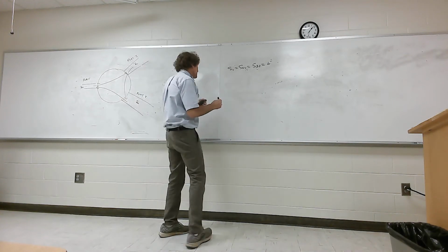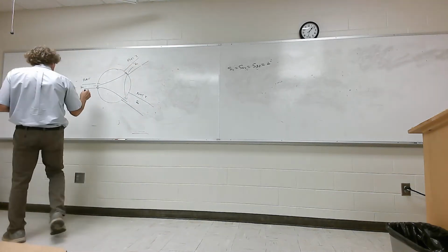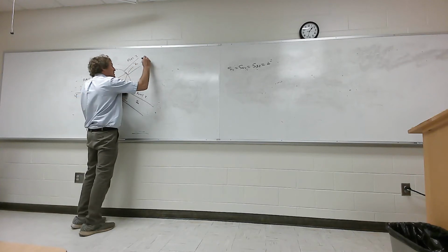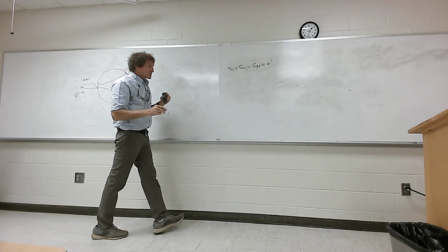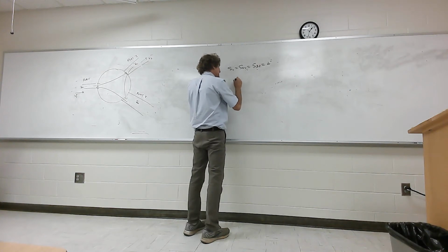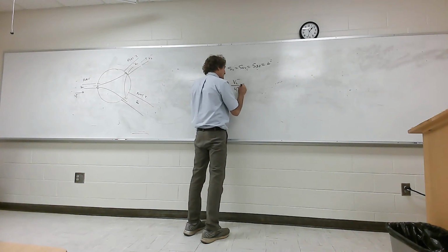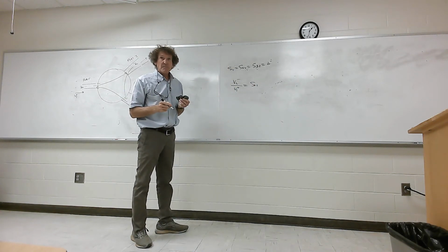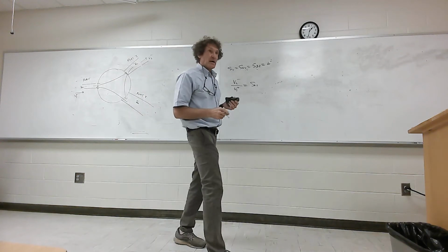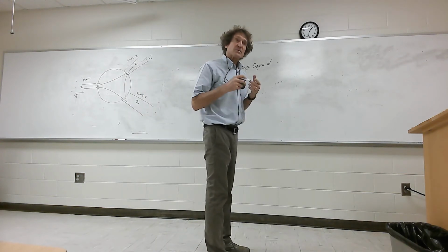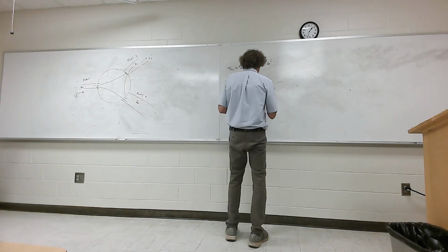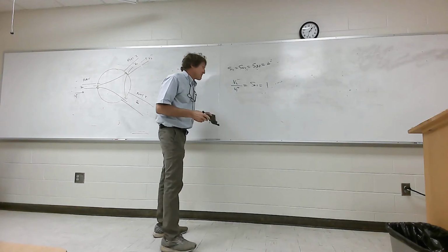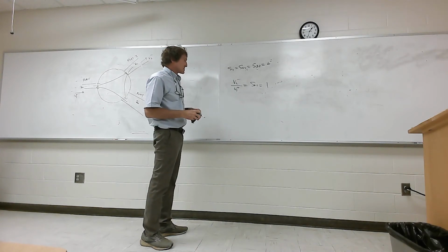So if V1 plus comes in here, they want all of it to come out here, V2 minus. So when I take a look at V2 minus over V1 plus, that is S21, isn't it? By definition. You all agree with that? If you don't remember that, that's okay. You've just been exposed to this. So that would be equal to 1. You all follow me? The reason is that that's the definition of S21. It's assuming that everything's matched otherwise.